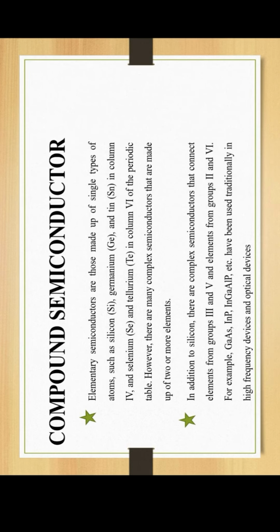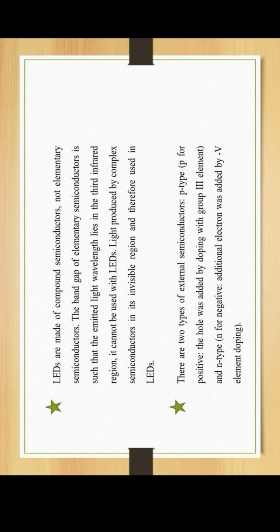LEDs are made up of compound semiconductors, not elementary semiconductors. The band gap of an elementary semiconductor is such that the emitted light wavelength lies in the infrared region. It cannot be used with LEDs. Light produced by complex semiconductors is in the visible region and therefore they are used in LEDs.